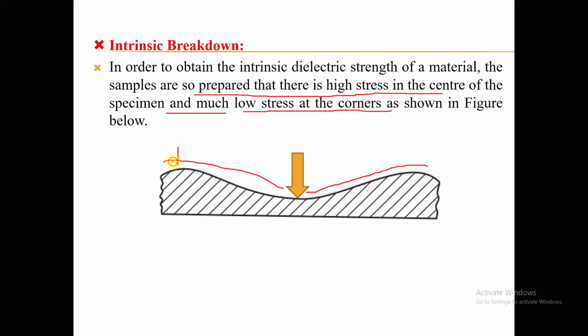So this is the low stressed region, whereas the highest stress is applied at the center point of the given dielectric material to determine its intrinsic dielectric strength.